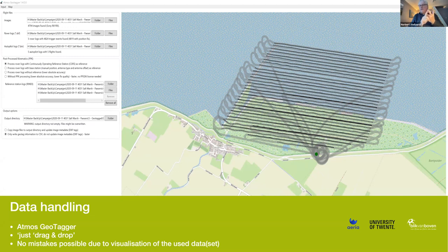The other data stream is your PPK rover data, the data from Marlyn itself, the PPK correction data. You also have the autopilot data, and that's an important one because the autopilot data will tell the geochecker system in which angle or heading the machine was in flight. So that's what you need for corrections on your PPK also, of course.